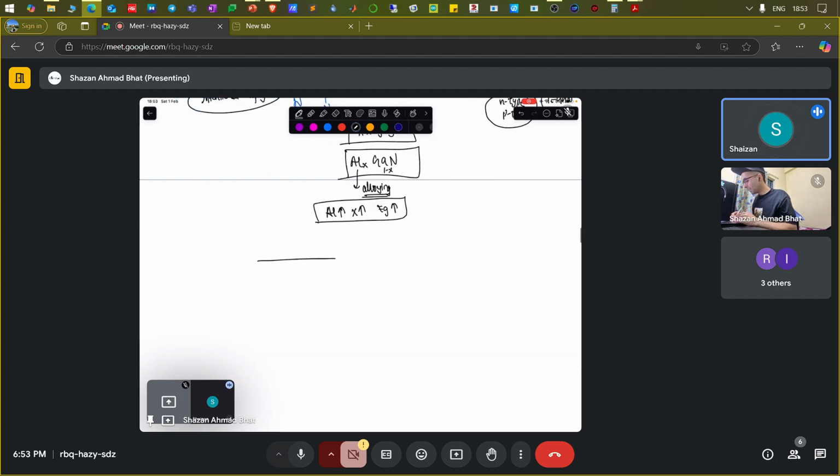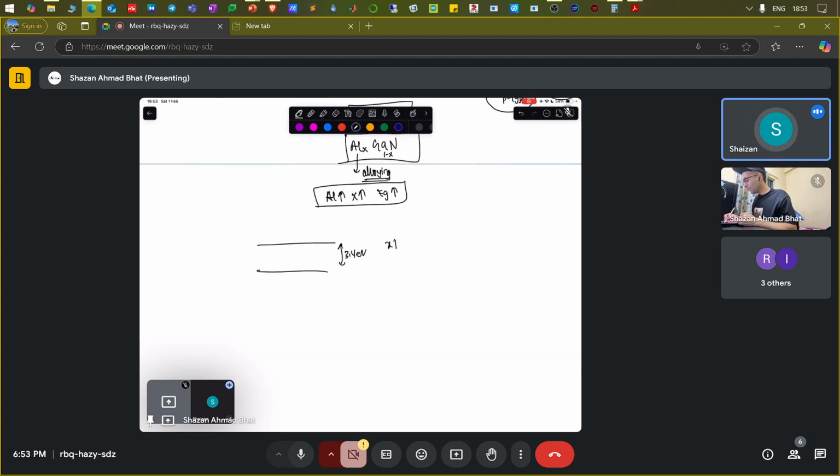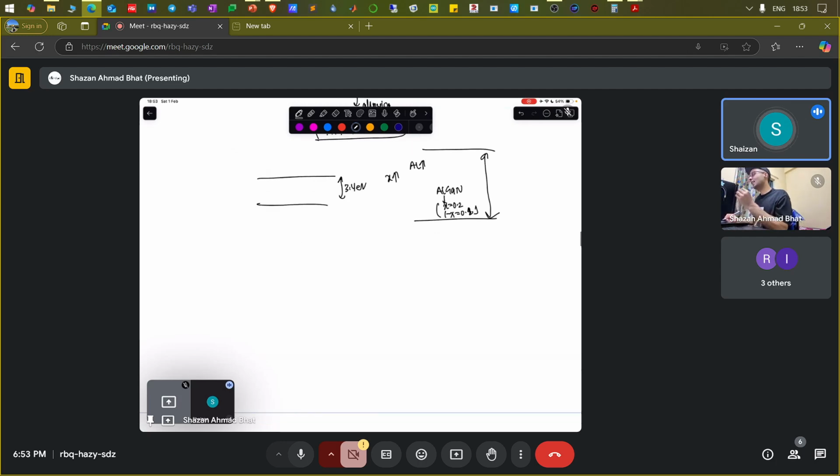That means if you had, let's say, gallium nitride of 3.4 electron volt, and you start to increase X, you start to increase the aluminum concentration, the band gap starts to increase and becomes much greater. And it finally becomes aluminum gallium nitride, let's say if X is equal to 0.2, and that means 1 minus X is equal to 0.8, which is basically the concentration of the aluminum and the gallium. And if X is equal to 1, and 1 minus X is equal to 0, that means it will become aluminum nitride.